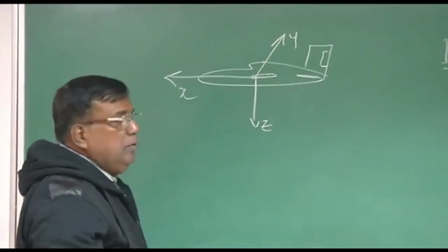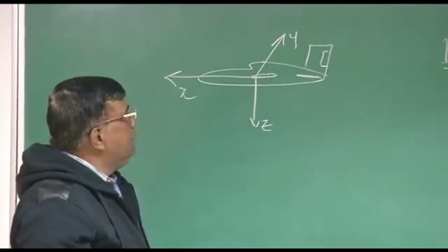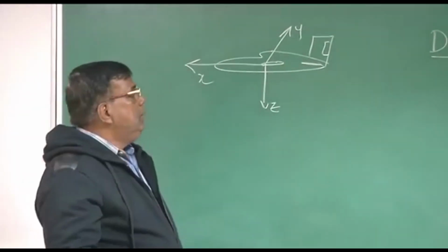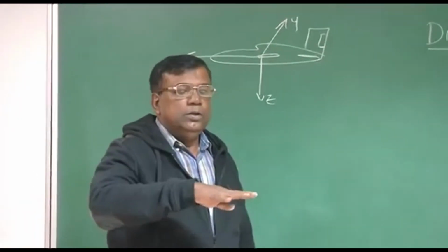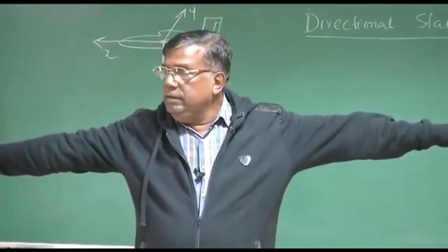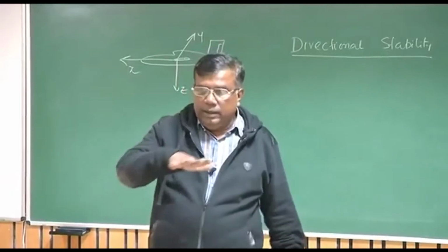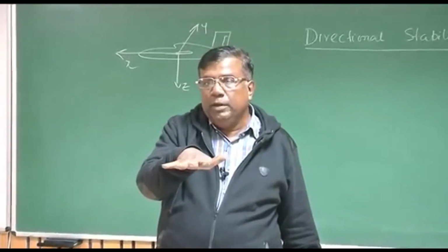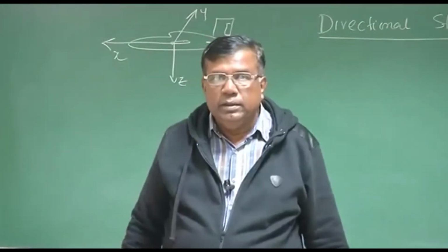And we know that when we are discussing longitudinal static stability, we are talking about motion about the y axis, that is pitch up, pitch down. But now, once we are talking about directional stability, we will be talking about motion about the z axis. And the convention is, if these are the two wings, if the right wing is going back, the yawing moment is positive, and if the left wing is going back, the yawing moment is negative.